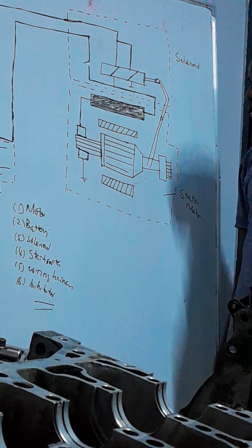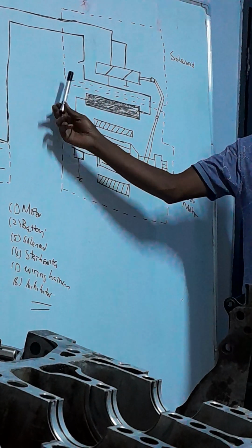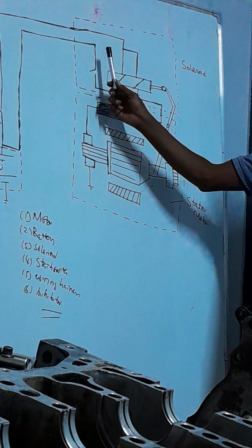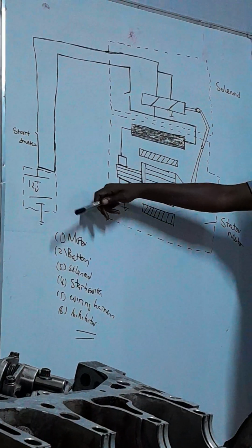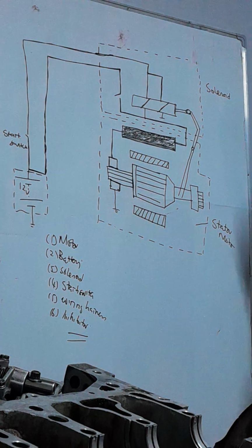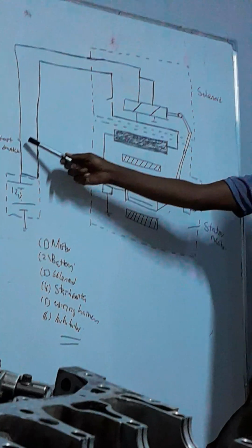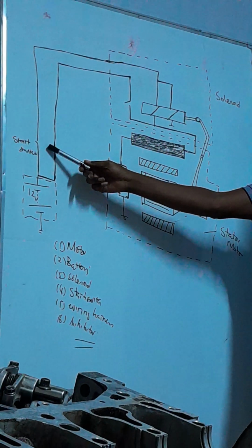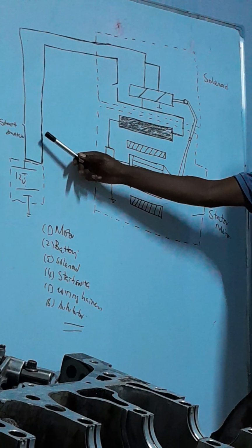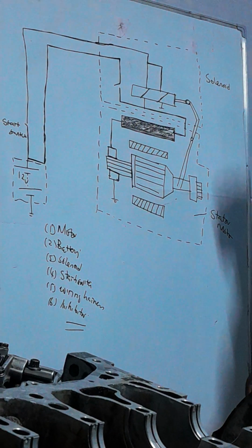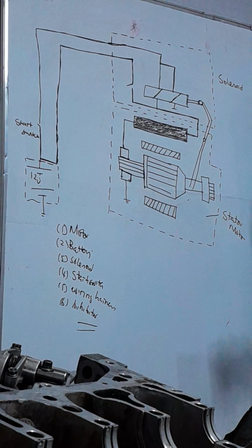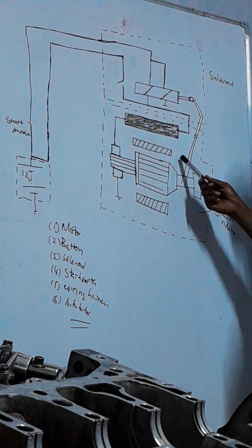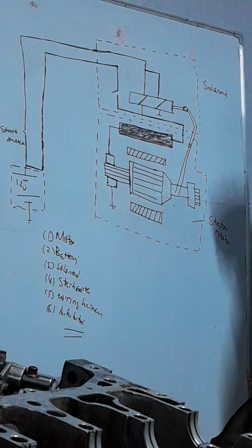The start switch, the driver operates the system using the start switch. It is part of a multi-stage switch, and the last stage of the ignition switch is the start switch. It is spring-loaded. When the engine starts, the driver will release the start switch and it will roll back to the on position. Then the engine will continue running with the starting system switched off.